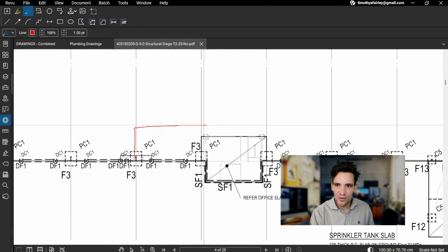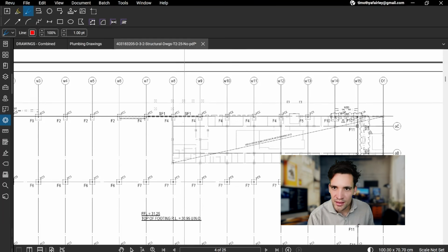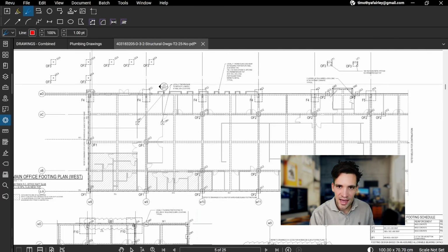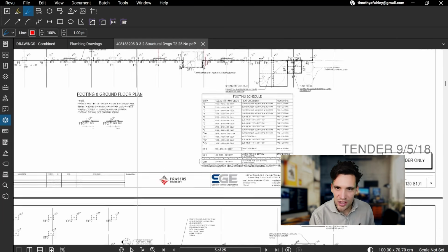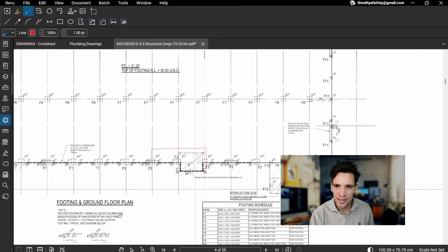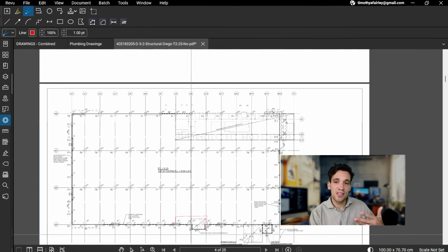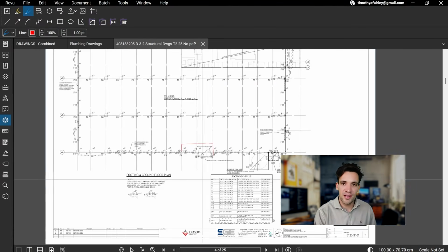This close-up view is actually a little bit like that because we can see it goes from W8. So W8 is the edge of this slab. You can see that is that grid line. And then you can see the slab comes out just before W9, which is what is being shown here. So this is how we relate drawings to each other. And this is a useful concept to understand. And they're also going to be in longitudinal and latitudinal.